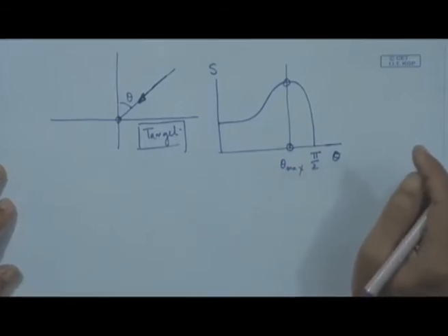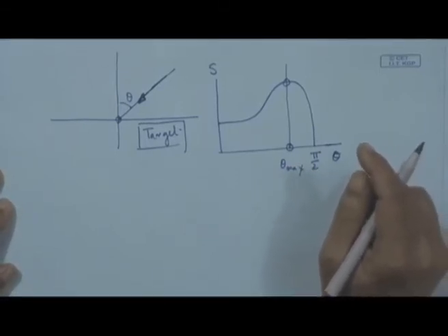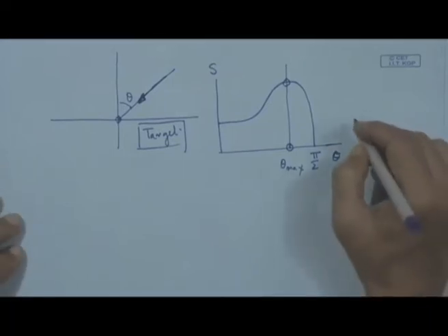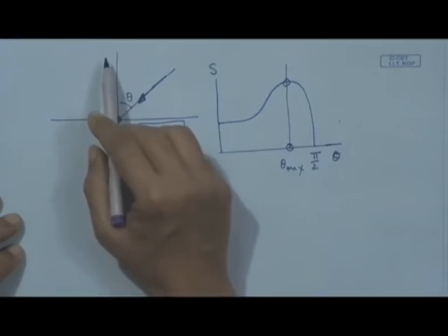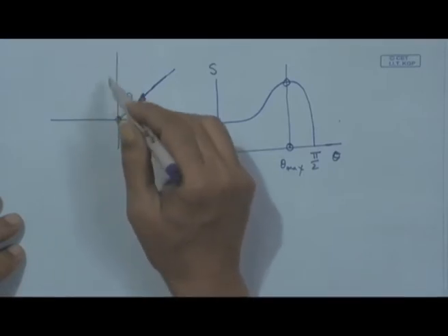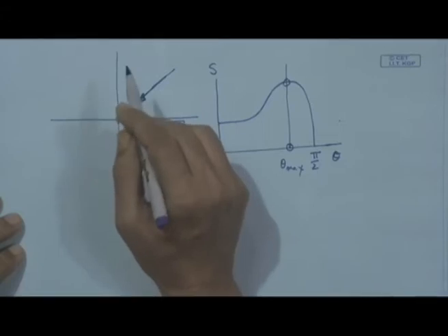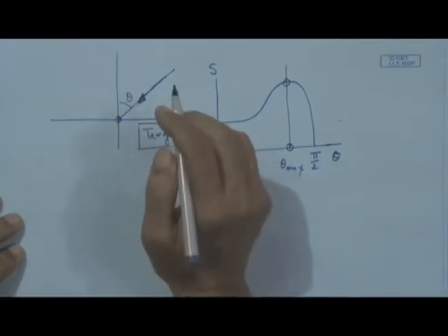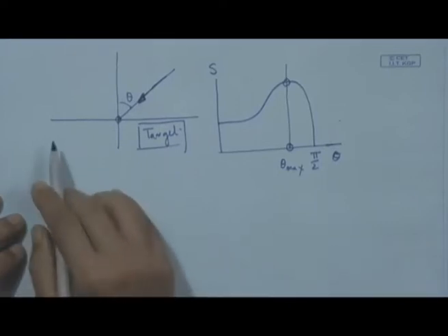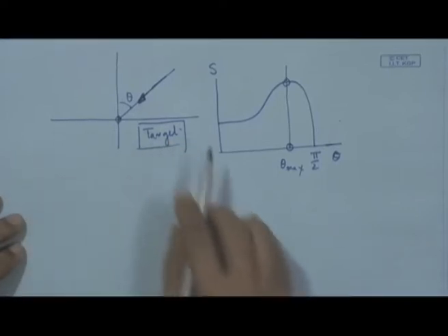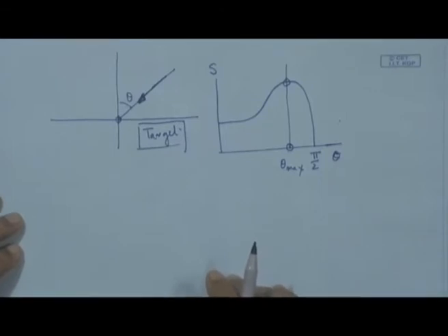Now, normally we usually consider a normal angle of incidence, so the argon ions strike under the action of the electric field normal to this surface. But this surface that we are showing is a theoretical one, that means it is optically flat and horizontal, but in practice this is not the case.